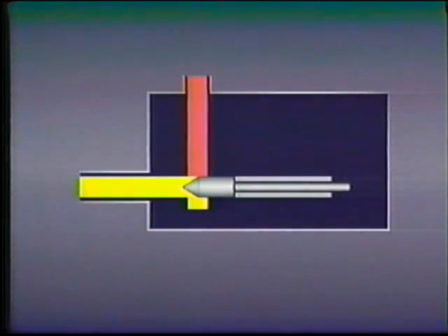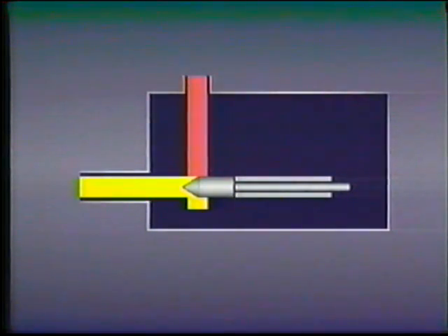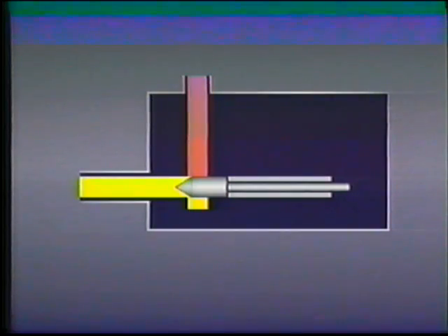In some valves, the temperature compensator is an aluminum or bimetallic rod connected to the movable part of the variable orifice. Aluminum expands more with changes in temperature than steel does. As the fluid gets hot, the rod lengthens, reducing the size of the flow path past the orifice. The hot fluid flows more easily, so the flow rate through the restricted orifice is the same as the flow rate of a colder fluid through a larger orifice.